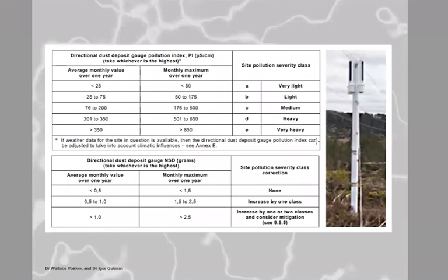We can use dust gauges to get it, directional dust gauges, where we measure the pollution from different directions, capture it into the dust gauge, and then from there we can determine our environmental pollution levels. Very cheap. You're looking at about under $300 for a set. When you put on top of that a surface conductivity little device, which is energized every 10 minutes at 600 volts, you measure the current, you get the surface conductivity, and you can get your pollution severity levels at 10-minute intervals. There you're looking at about $2,700 for a device.